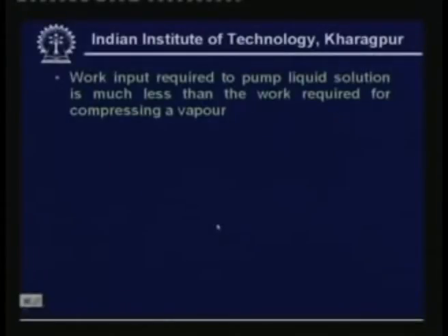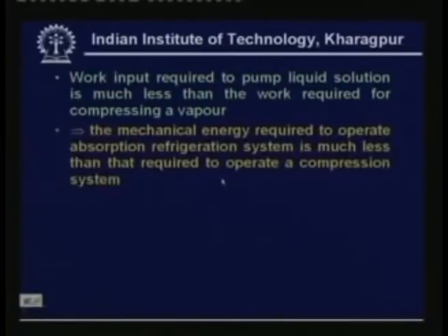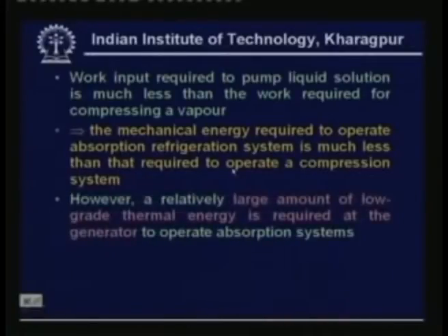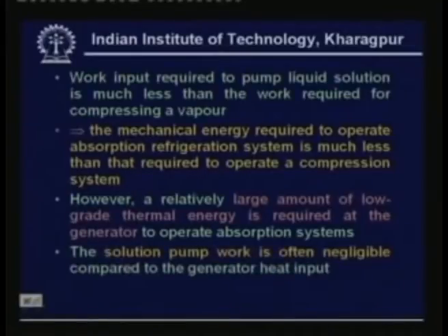So, that is what I have mentioned here. Work input required to pump liquid solution is much less than the work required for compressing vapor. So, the mechanical energy required to operate absorption systems is much less than that required to operate a compression system. However, of course, you have to pay somewhere. So, instead of mechanical energy, you have to supply a large amount of low grade thermal energy to operate the absorption system. And as I said, the solution pump work is often negligible compared to the generator heat input.